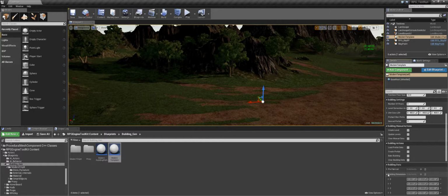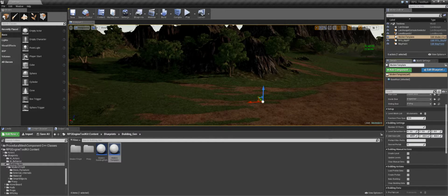For the definition of an actual given tile, by default, with the template that I have for the modular parts, each modular part is 400 by 400 by 400 for the height, width, and ceiling height for my pieces, and everything for that tile has to fit with the same dimensions for it to piece all the modular pieces together properly. If that is off, then you may get gaps in between floors, between tiles, and things like that. But as long as you set up the modular pieces correctly, it will put them together properly.